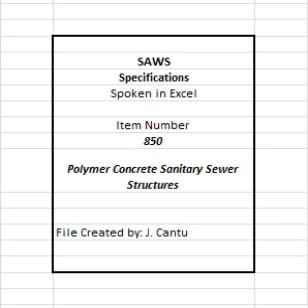C. Milestone 3, 20% of LS, sanitary sewer structure encasement and testing. This pay item includes structure concrete encasement, rebar, HDPE throat/grade rings, ring and cover, surface restoration, and includes all structure testing in accordance for leakage, separate and independent of all other sanitary sewer piping. Furnishing and placing all materials necessary to complete the work is included in Milestone 3 and must be completed prior to payment, 20%.